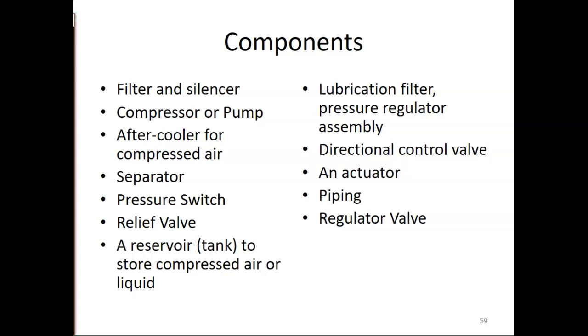With hydraulics, we don't have to worry about it. It is a lubrication fluid in and of itself. With pneumatics, we typically are pulling every last little bit of anything that could possibly be in the system out of it through a bunch of filters, right? Which means the air is very dry. So think about air during winter time. What happens to your skin, to your lips, and everything else during winter that doesn't happen during summer when everything's nice and hydrated?